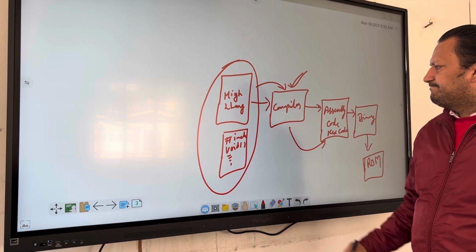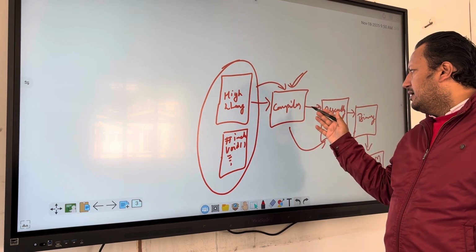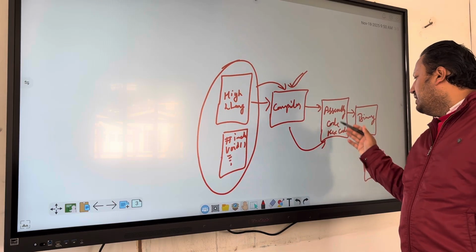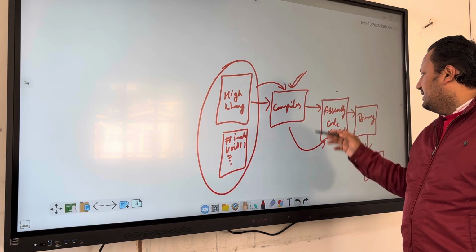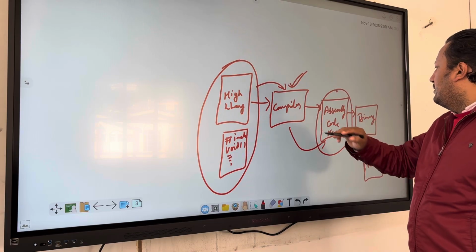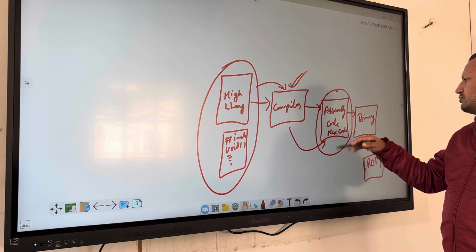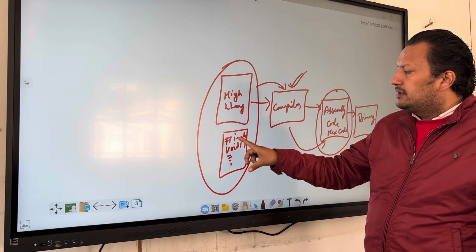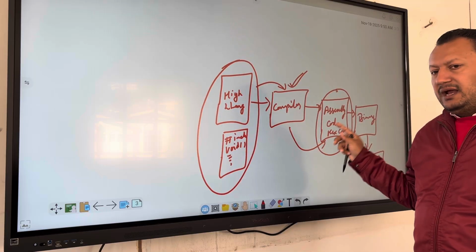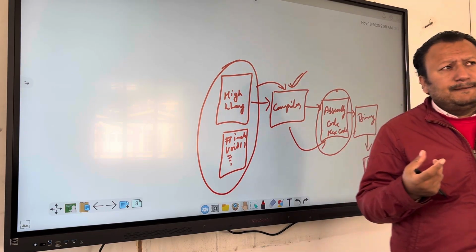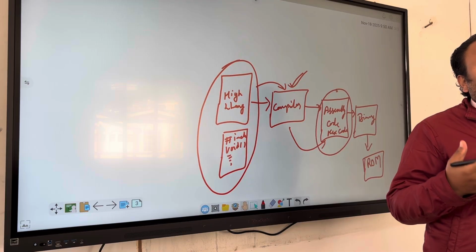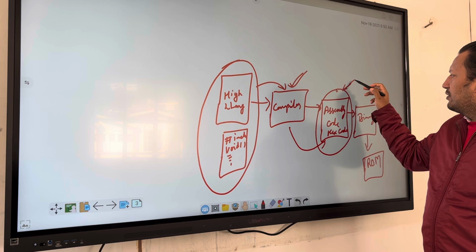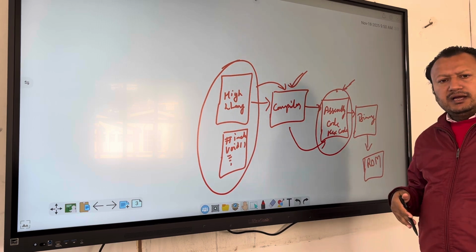So with high level language, the compiler converts it to the particular device's assembly code, and from there the assembler will convert it to our hex code. And there is one more thing: when the compiler converts the C language to hex code, it generally makes a bigger file than a normal programmer will make for assembly hex code.